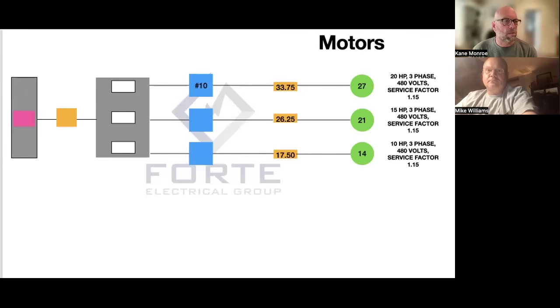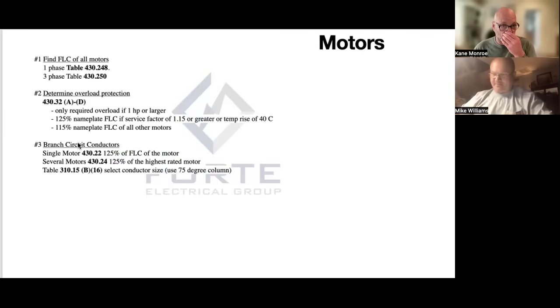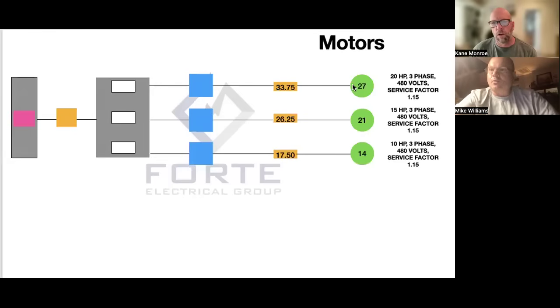I told you I'd not show you that answer. 430.22, take 125% of the FLC of the motor. So we go back to the 27. It's 27 times, what was it? 1.25.